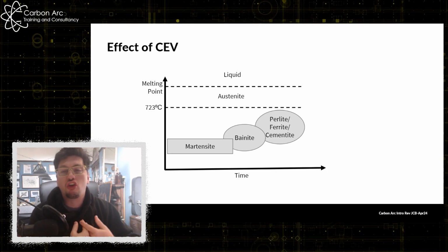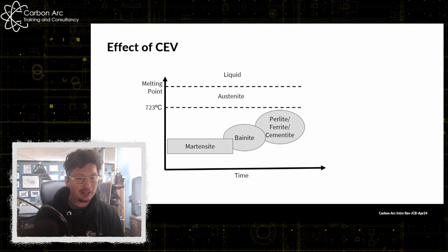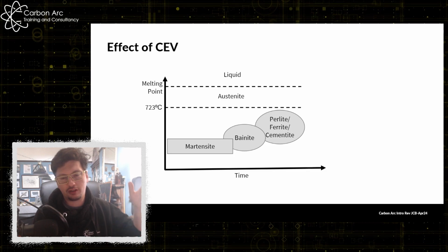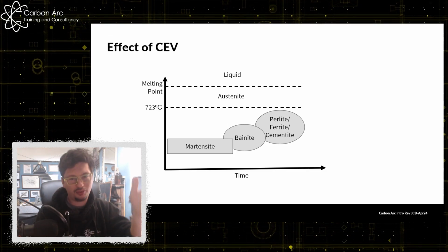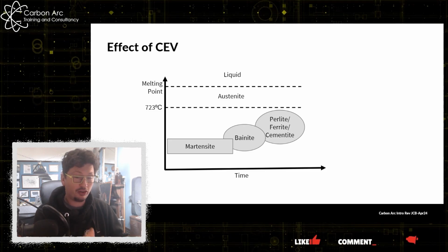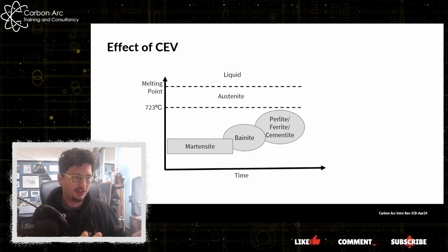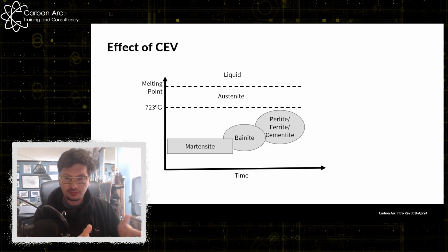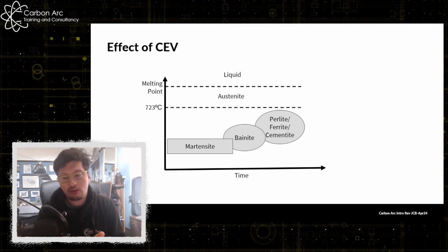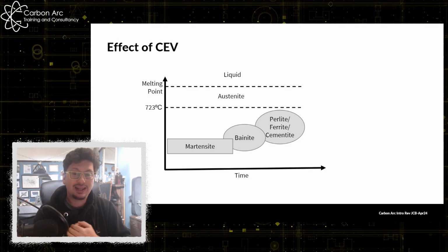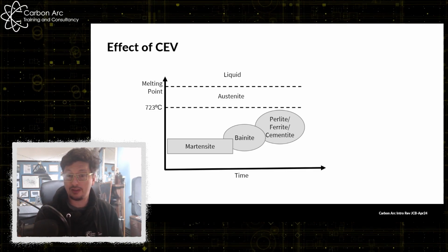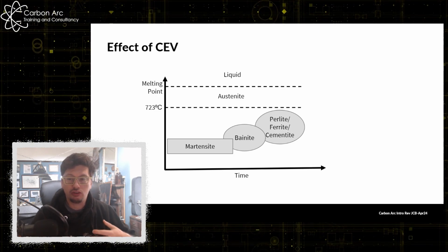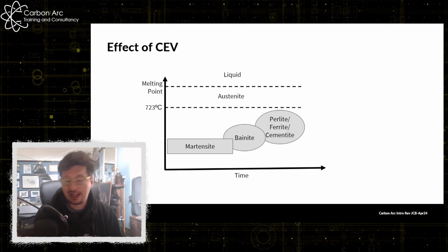Now, I keep using the term carbon steel like it's all one thing, but we know it's not. We have different grades of carbon steel. We start at S235, 275, up to 355, which are our general fabrication, general purpose steels, if I can give it that term. But we go up in strength as well. Now, one of the ways we can increase strength, let's say from an S355 to a 690, which is a really high strength steel, would be to add more carbon.